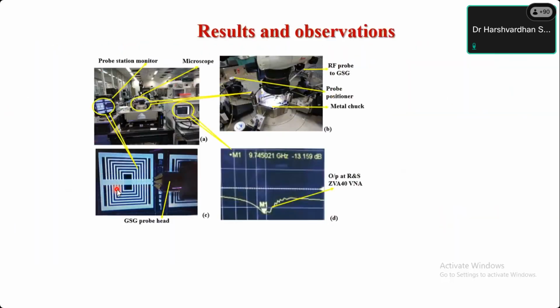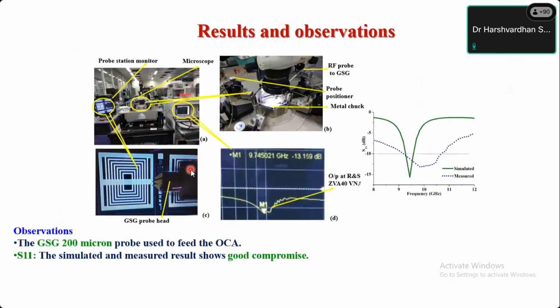And the wafer thickness is very small, it is very thin. We cannot use a simple RF connector. So GSG probes, specific probes, are used during the measurement. And in the same way, to make it more practical, you also have to use a CPW feed instead of a normal microstrip feed when you are designing the on-chip antenna.